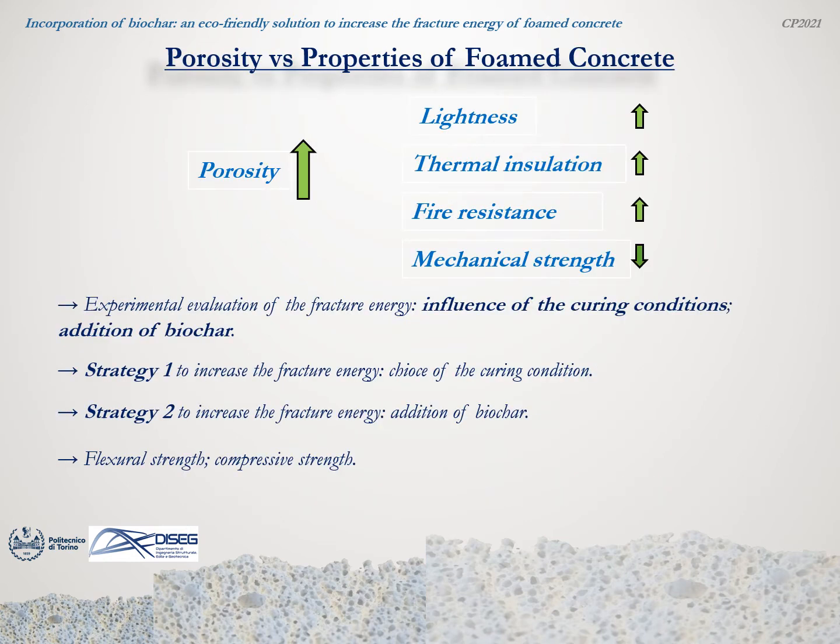An increase in foam's volume in the mix proportion will lead to a decrease in cementitious material's density and consequently to an increase in its porosity, since air bubbles will occupy a greater part of the volume. Density and porosity play a fundamental role in defining properties of foamed concrete. The higher the porosity, or that is the same, the lower the density, the better the properties of foamed concrete in terms of lightness, thermal insulation, sound absorption and fire resistance, which are characteristics of absolute importance in the building sector, but, on the other hand, the worse the mechanical strength.